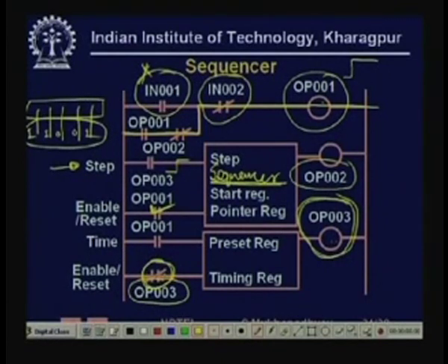So, a step is executed in the sequencer, and because it is latched like this, immediately when this goes high, this becomes reset again, and once it is reset, this one is enabled, and therefore it is again timing. It is continuously generating timing intervals, and at the end of each interval you get a pulse which executes the next register in the sequence of the sequencer.